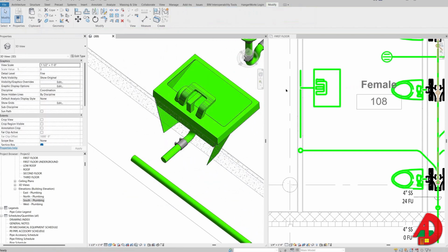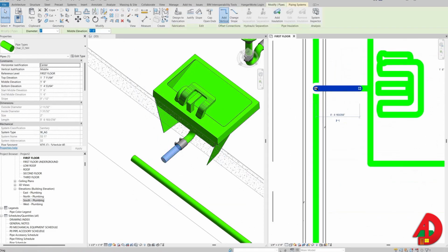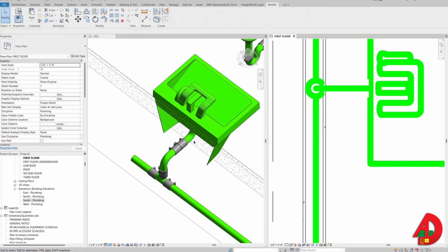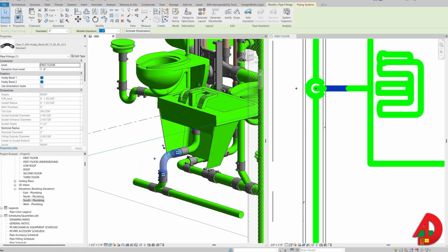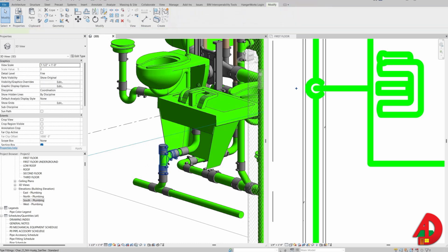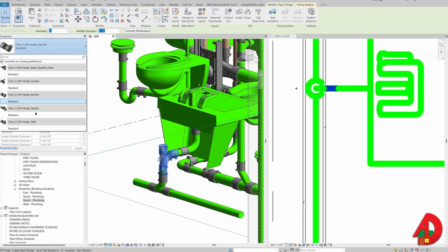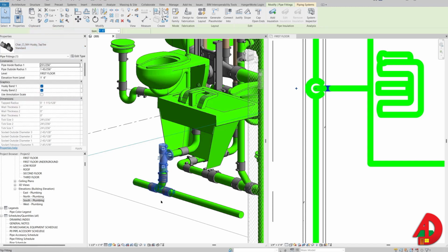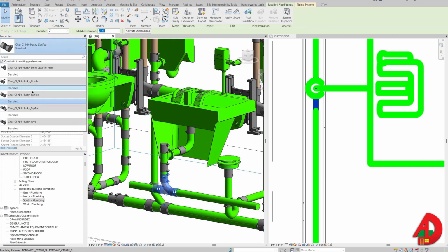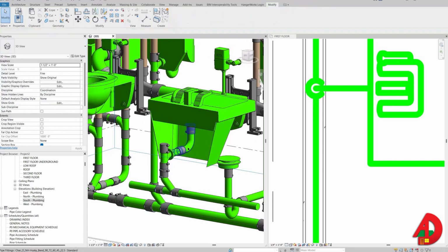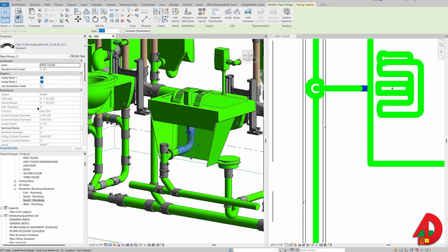And it is easier to go back to my plan view, drag this line backwards and then forward again to connect to the pipe below. When selected, this fitting shows a tiny plus button that when I click on it turns into a sanitary T, and I can replace it with a tap T. Again, the direction of this fitting is wrong and also has to be a combo. And also, since this is a lavatory, I will need to show a P-trap.